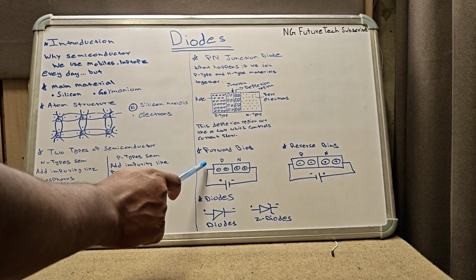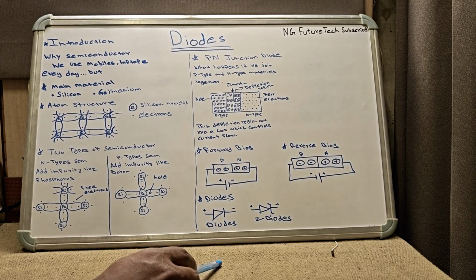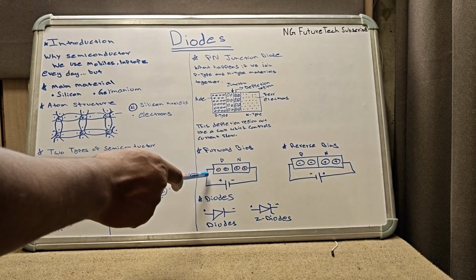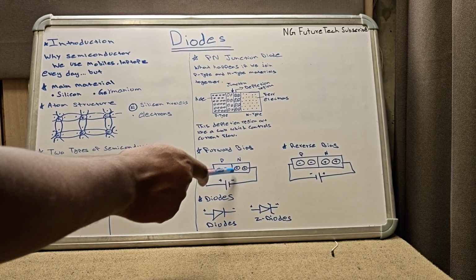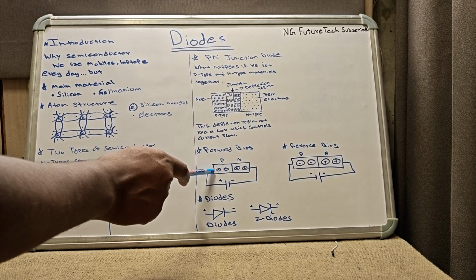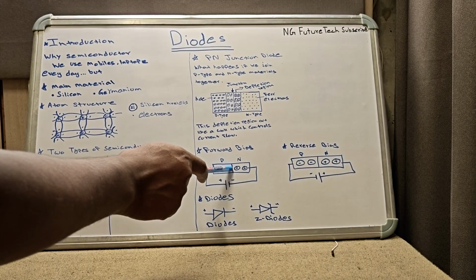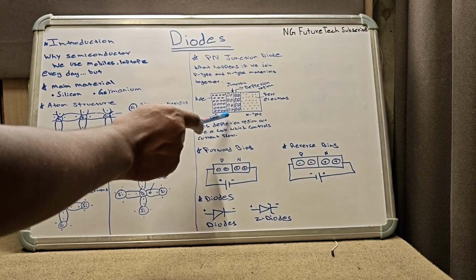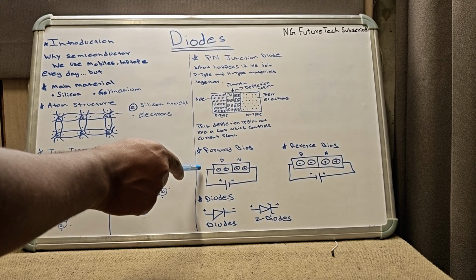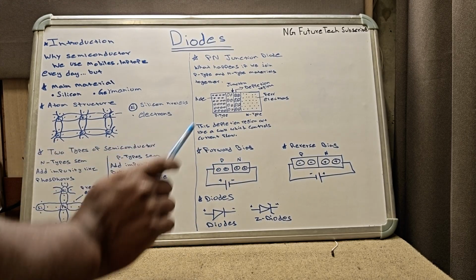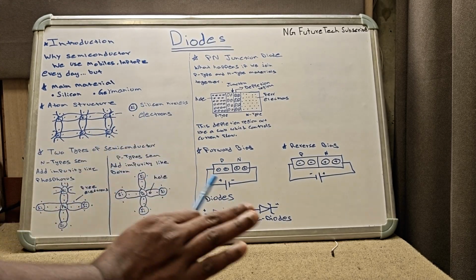Forward bias is used for electronics: positive is connected to P-type and negative is connected to N-type. When electrons flow, they will be pushed through this and break this PN junction wall. Minimum 0.7 volt is needed to cross this wall, otherwise this device will not work.